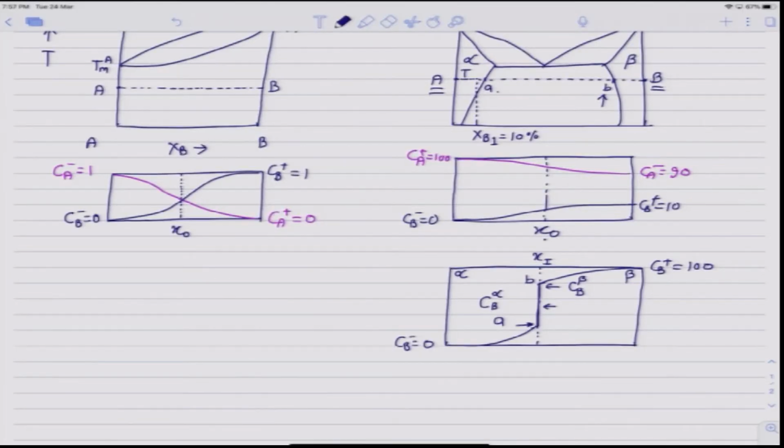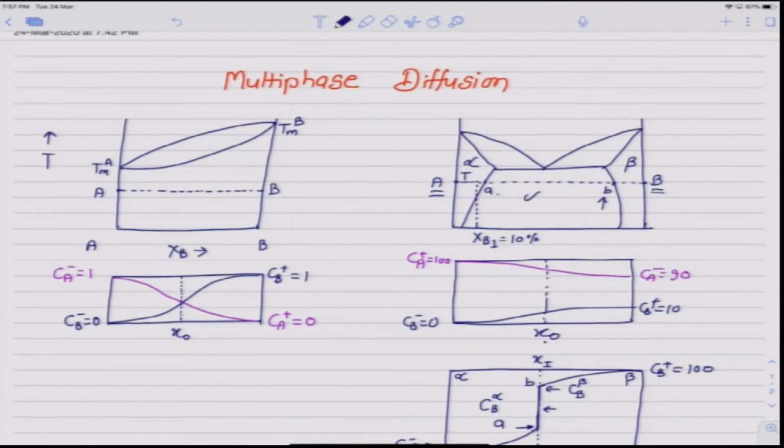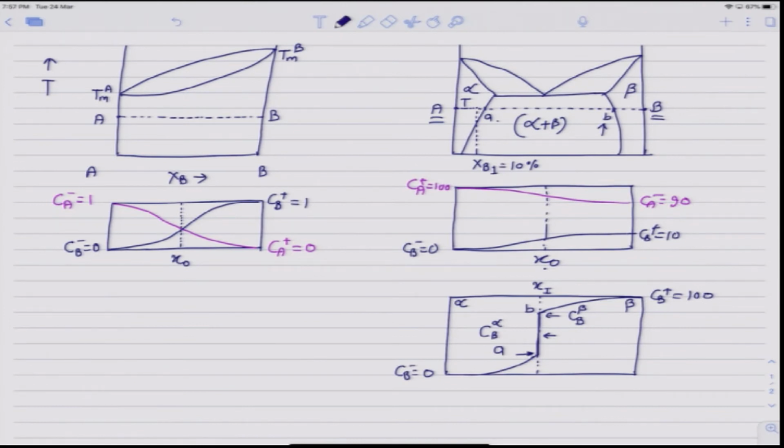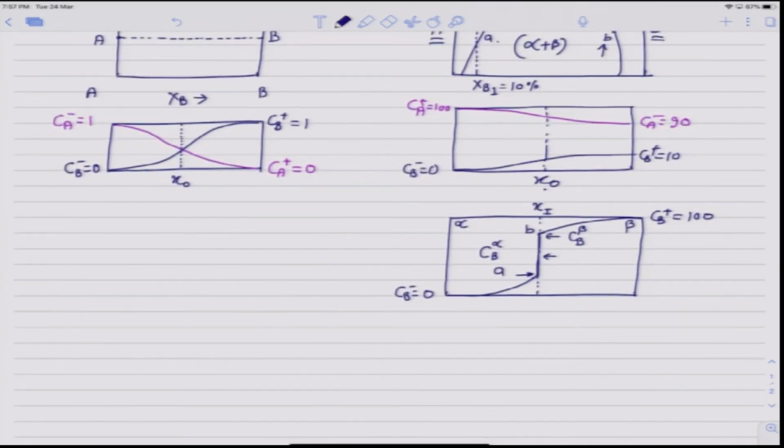and we exactly get the tie lines between those two. Now, the question is, we see a two-phase region on the phase diagram here, but when I draw the concentration profile or the diffusion structure, I did not show a two-phase region, and the reason is because this is a binary system. Again, if we apply the Gibbs phase rule, F is equal to C plus 2 minus P, and since I am considering constant pressure and the diffusion couples are isothermal couples, that is at constant temperature, I can ignore this factor 2, which is basically for pressure and temperature,